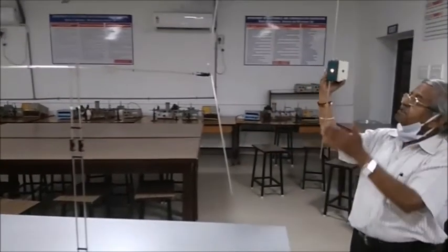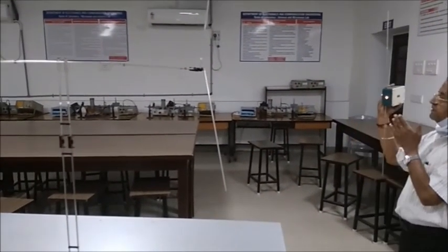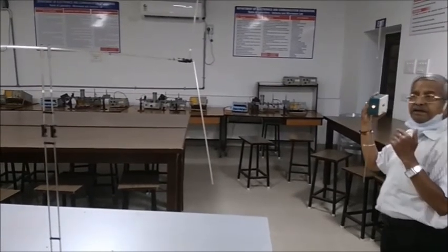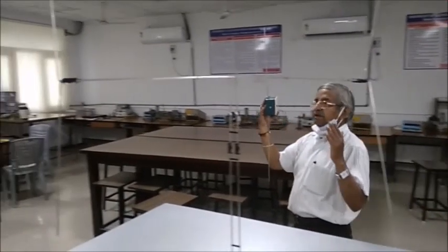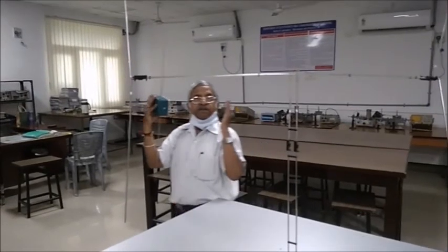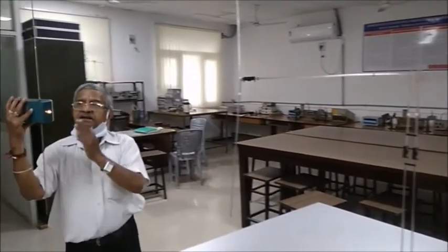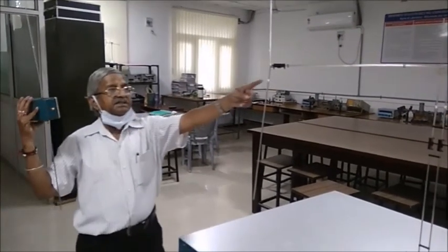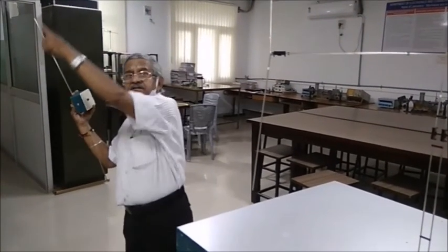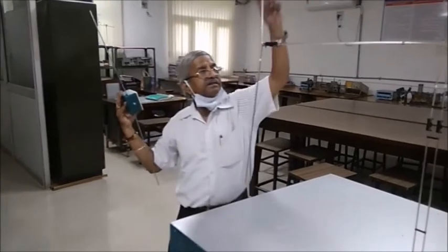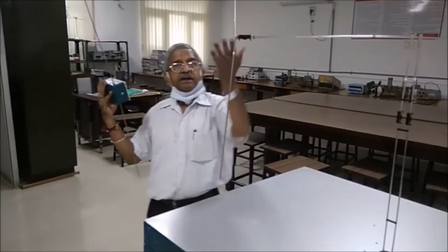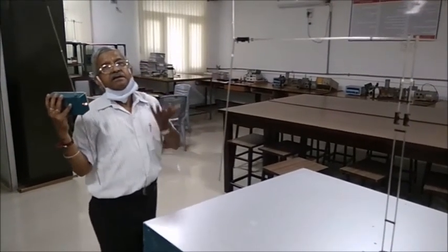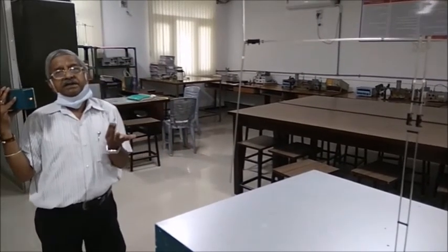This is vertically mounted, so now the radiation is from the end. In the same way, along the horizontal there is no radiation, but at the end there is radiation. So I can say the polar pattern is from the center to the end, and the same way at the other end. So I can call it the end fire antenna. It is also a directive antenna.